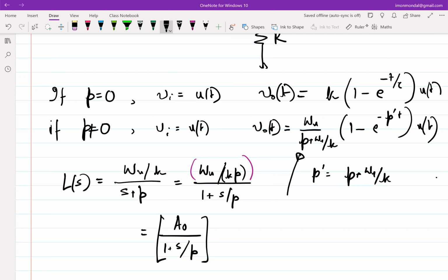If you plot the loop gain, and the input is DC, you should be able to read off the loop gain value at whatever frequency you are interested in, and from that you can figure out what the steady state error is supposed to be. If it's supposed to be DC, then you look at the loop gain value at DC. If it's not DC, then you look at the loop gain value at that particular frequency. So by this logic, the steady state error is proportional to 1 by mod of L.